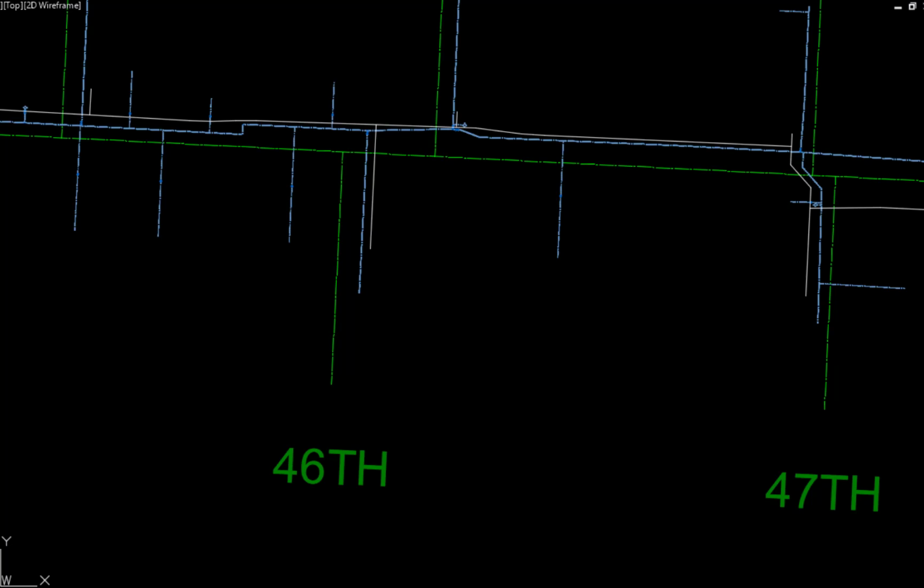Either concrete thrust blocks or pipes with restrained joints are used at bends to counteract the hydraulic thrust forces and prevent pipe pull-out at bend joints. I have experienced problems with thrust blocks and prefer the use of restrained joint pipe. In order to prevent pipe pull-out at the joint where the new pipe is connected to an existing water pipe, a minimum of 40 feet of new pipe is required to be installed in the same alignment as the existing pipe prior to any bend.